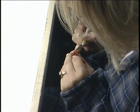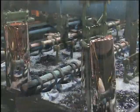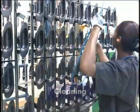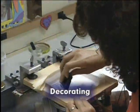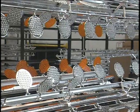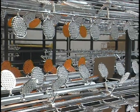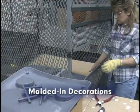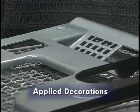But many plastics finishing processes are performed for aesthetic or appearance purposes. These finishing processes are the primary focus of this program and include degating, deflashing, cleaning, and decorating. Virtually all plastic products require some decoration. The methods of decorating molded parts include molded-in decorations and applied decorations.